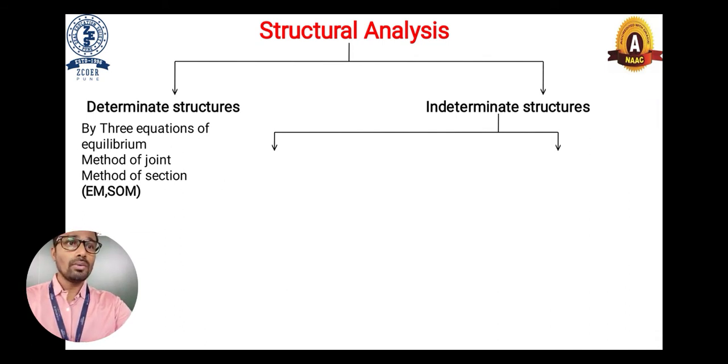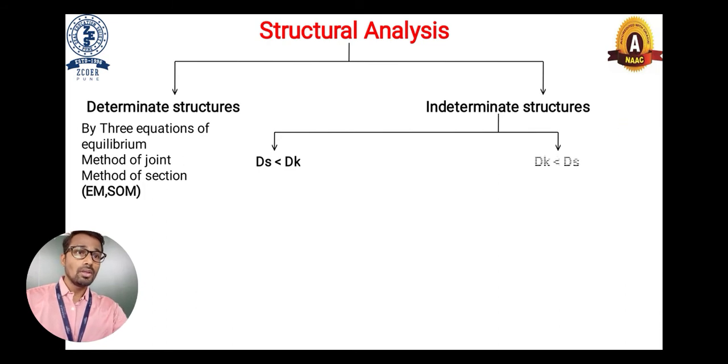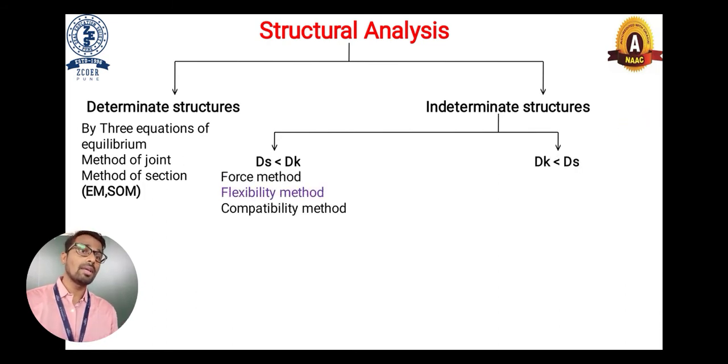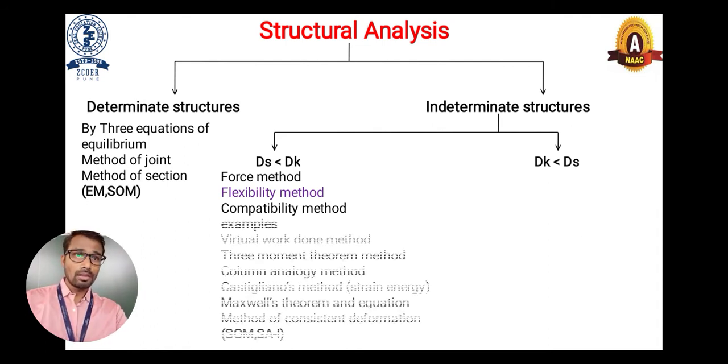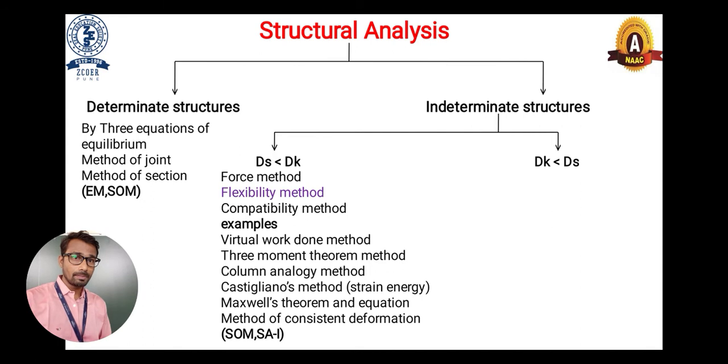Okay, now indeterminate structures, where the degree of statics is greater than the degree of kinematics, and the degree of kinematics is greater than the degree of statics. So you can deal with the case when the degree of statics is less than the degree of kinematics. The force method, flexibility method, and compatibility method have been covered in Structural Analysis 1. Some examples are virtual work method, three moment theorem, column analogy method, Castigliano's, Maxwell's. This has been done in strength of materials and Structural Analysis 1.